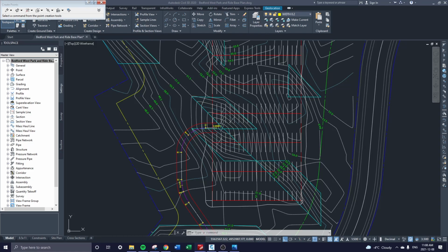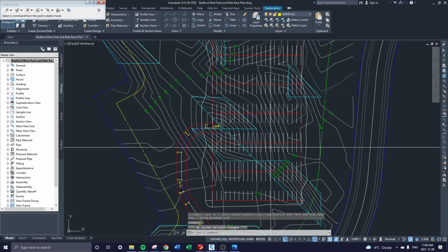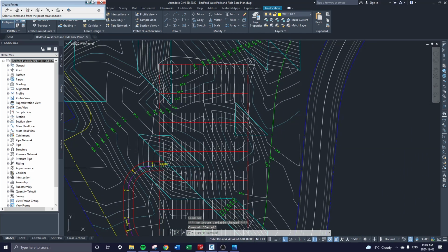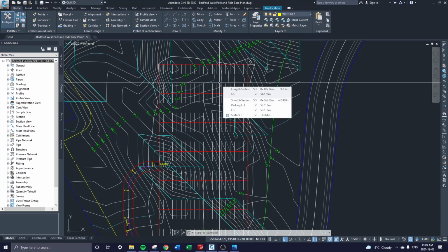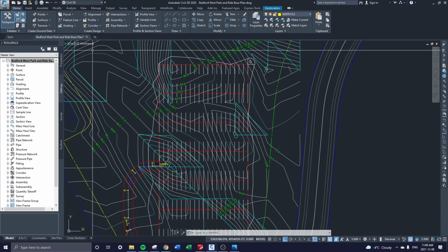We'll look at one of his, that doesn't even have, is that his site plan? I don't know. Sorry, I'm just looking through his thing here. Okay, so your site plan needs to have the alignment, that table, parking lot with dimensions, and coordinates for the parking lot corners. And that must be it. So I don't know if you have to do finished grade elevation points. I'll show you how to do it in case you'd like to include it. Just be wary if you include them to label them and say, hey, this is the finished grade.